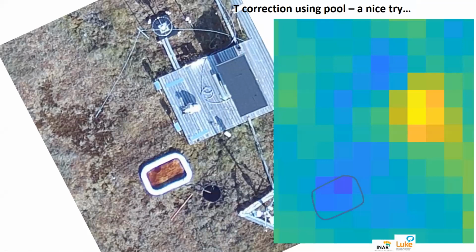So when I'm flying at 500 meter altitude and looking down, the minimum pixel size is 61 centimeters. So the water pool should ideally be at least 4 by 4 meters. Well, considering some uncertainty in the location of the pixel, after georeferencing this might be enough. But yeah, I have to do some more Googling for Chinese water pools.